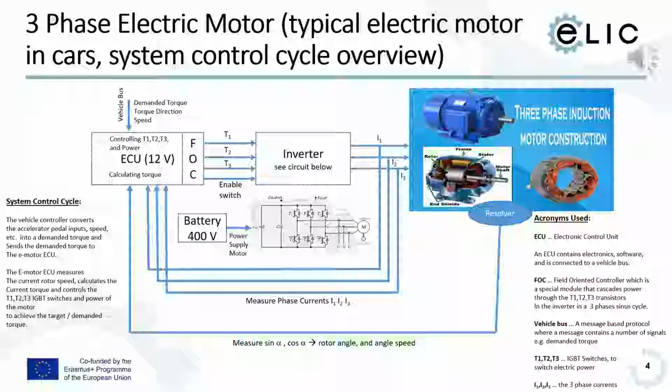If you put electric power on a coil, then you create a magnetic field that can drag the rotor inside the e-motor. And these three currents are going to three differently positioned coils that create three different magnetic fields that can drag the motor in a circle to create a rotation per minute by the rotor, which is then the rotation of the motor.